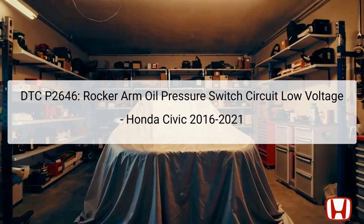This presentation covers DTC P2646, which indicates a low voltage issue in the rocker arm oil pressure switch circuit of the Honda Civic models from 2016 to 2021. The DTC suggests that the vehicle's onboard diagnostics have detected a potential problem with the system responsible for controlling VTEC, which stands for Variable Valve Timing and Lift Electronic Control.